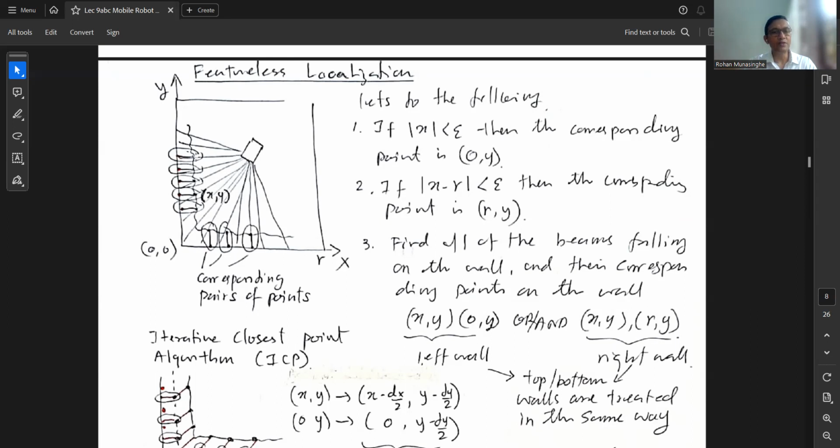right? And see, for example, any of these lines, right? You can see this curly line here. Let's assume this is what you see, your measurement of the wall, and robot thinks wall is there, but the actual wall is like this, straight wall, okay? And there's an error. This is the measurement error. And you know your position is over here on the curly line here. And you can first assume that the horizontal line from that measurement point to the wall gives you the actual landmark. That point on the wall can be considered as actual landmark. Okay, this is the first impression.